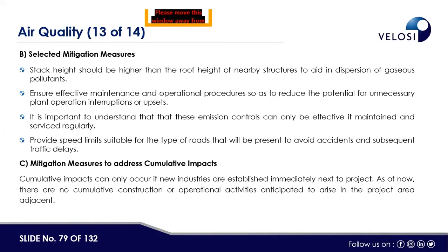Then we have proposed some selected mitigation measures as well. Stack height should be higher than the roof height of nearby structures to aid in dispersion of the gaseous pollutant. There is a particular standard in each country, or a particular standard for the company or the client as well. So the stack height should be higher than the roof height.